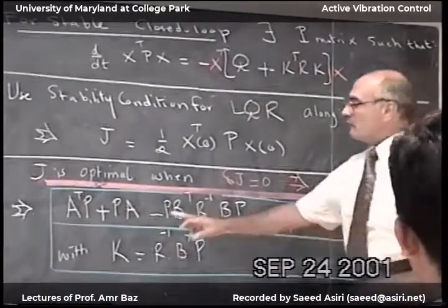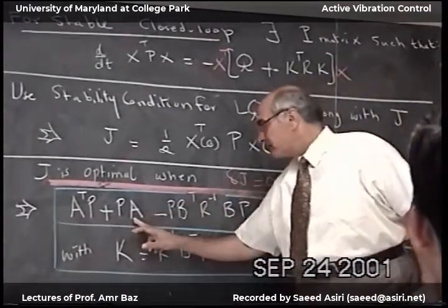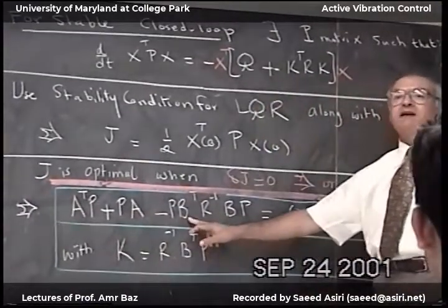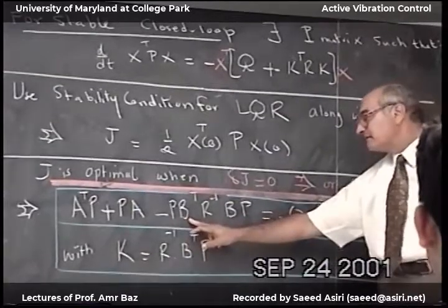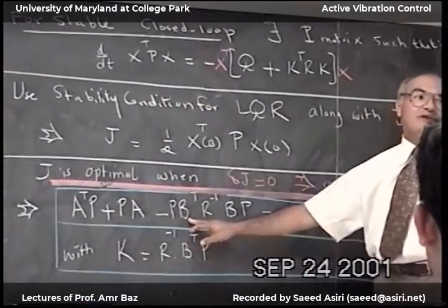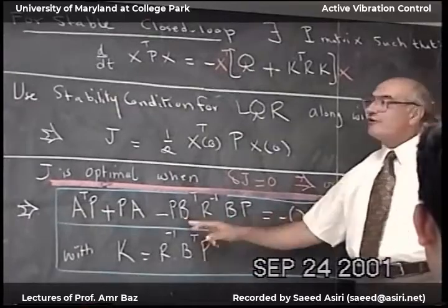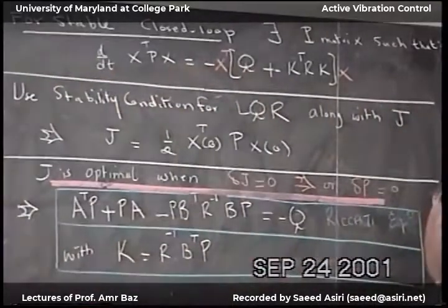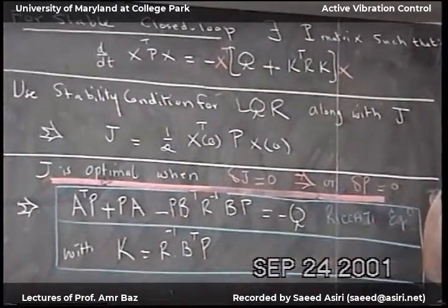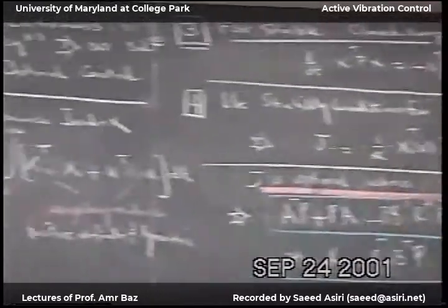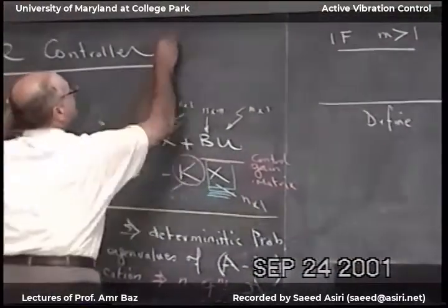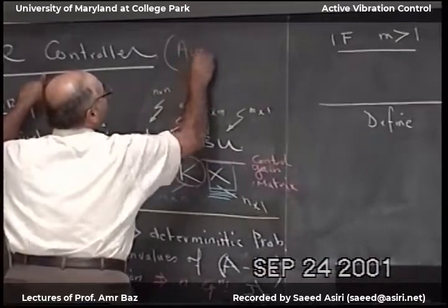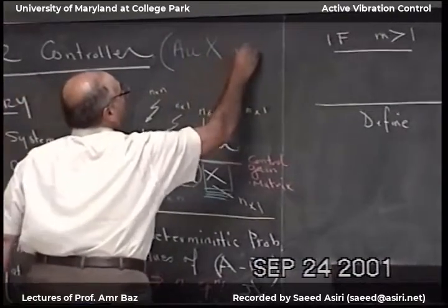Now, I have the open loop matrix, A. I have the input matrix, B, where the actuators are located. The sensors everywhere. We measure all the state vector. And the LQR assumes all X are available or accessible.